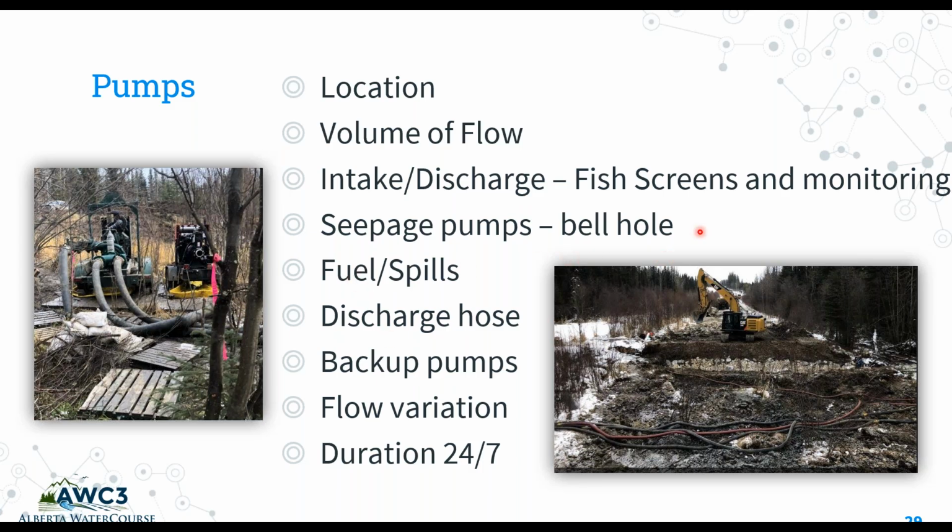Is your discharge above your downstream isolation? Seepage pumps are for bell holes, so when you install your dams, a lot of times they may leak or seep. So how are you controlling that water from coming back into your excavation? Fuels and spills: you want to make sure your pumps are in a location where they're easy to fuel. We've got spill drip trays. Do you have spill kits in the area?